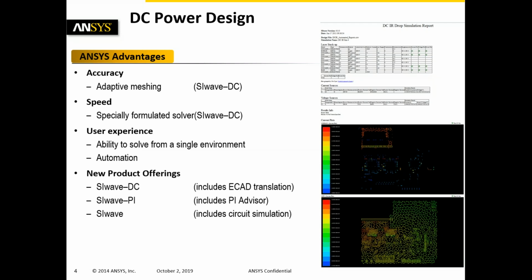SI Wave can include as many as signal integrity, power integrity, in frequency domain as well as time domain, S, Y, Z parameters, eye diagrams, bond wire analysis, and so on and so forth.